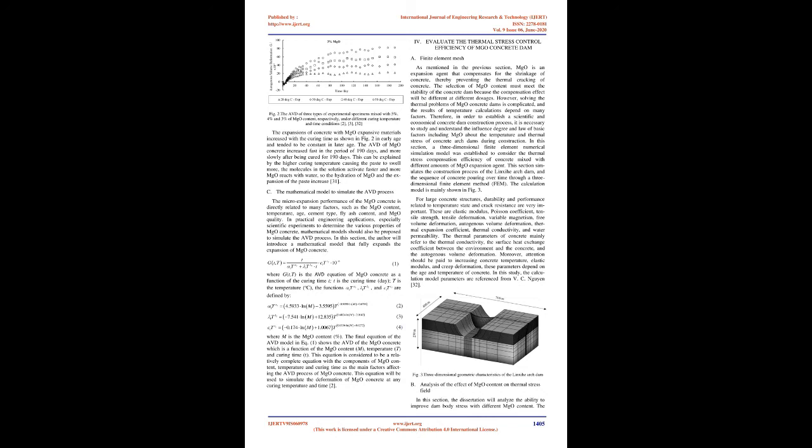Fine brucite crystals concentrated on the surface of the particles can produce large expansion, while brucite crystals in a large area around rough, dispersed particles cause a small amount of expansion. The expansion properties of cement stone and concrete mainly depend on the quality and content of the expanded materials, the ambient temperature, the type and amount of mineral additives, and the mineral composition and content of cement clinker.